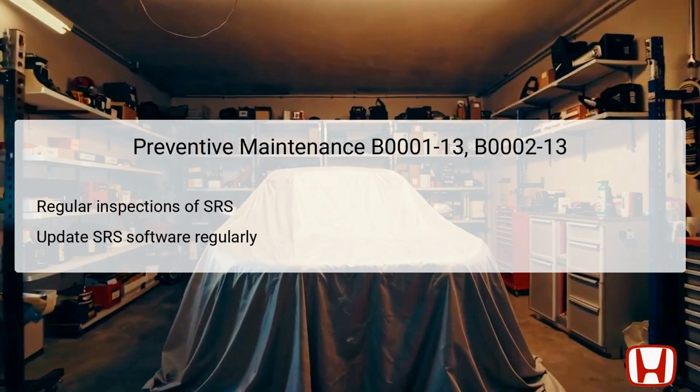Additionally, regular updates to the SRS software using the HDS are crucial, as these updates may resolve existing software anomalies and improve system reliability. Maintaining these preventive measures not only enhances airbag functionality, but also ensures passenger safety on the road. Educating vehicle owners about the importance of these practices can significantly extend the operational lifespan of the airbag systems, helping to avoid costly repairs and ensuring readiness in emergency situations.